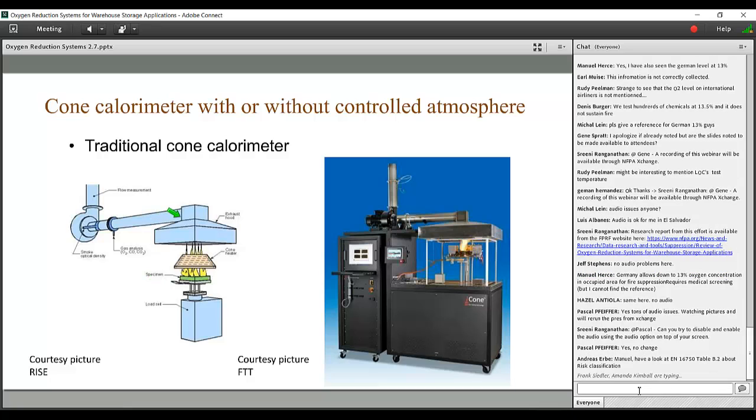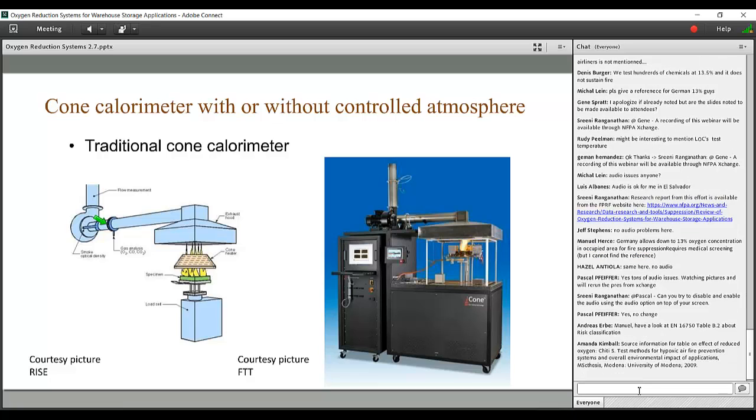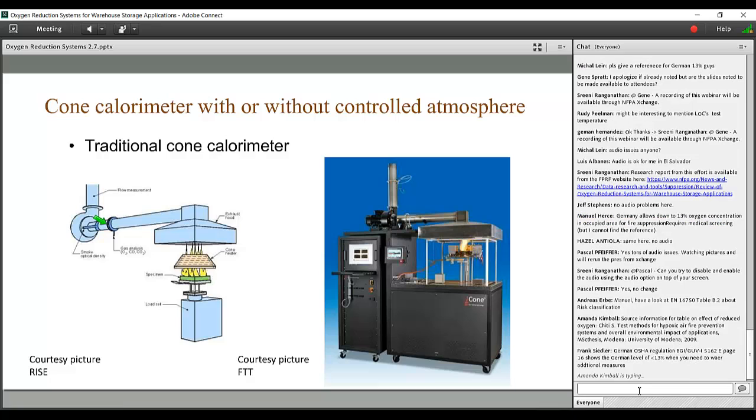All the gases are collected in the hood, which is indicated by the arrow, and in the duct connected to this hood there is firstly a gas probe which takes part of the gases to, for instance, oxygen analyzers, carbon monoxide and carbon dioxide analyzers, and possibly other analyzers if you want to look into other gases from fires, like HCl, HCN, and so on.